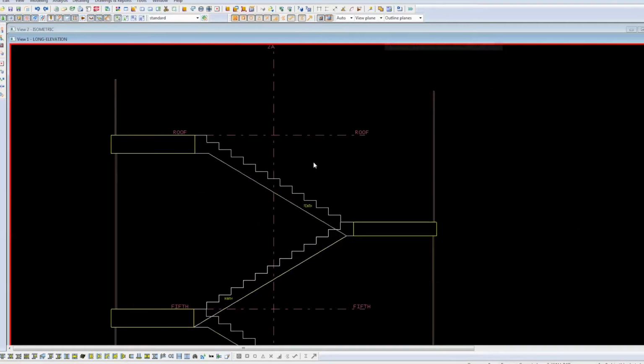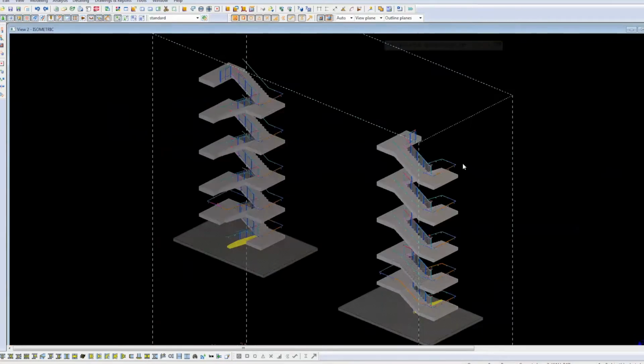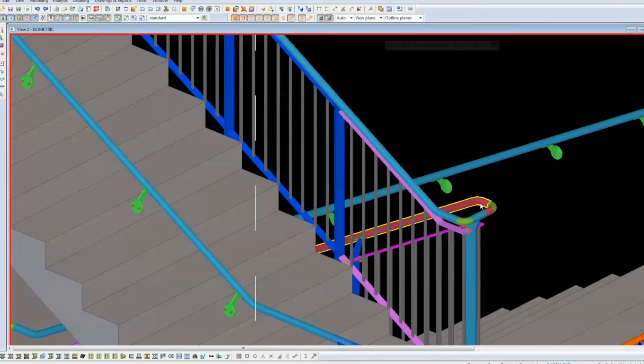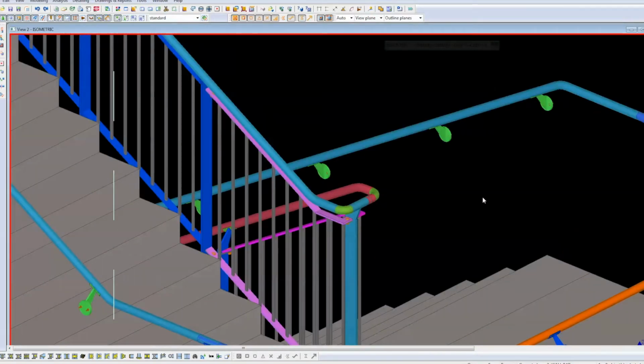And I'm using a contour plate. I've already decided from the survey information that all the width of the flights were all within 10mm of each other. This job in particular worked out well because all the handrails fit on saddles.